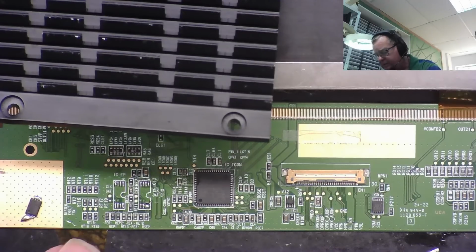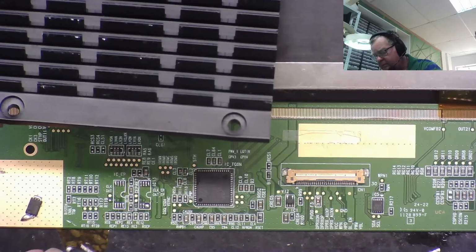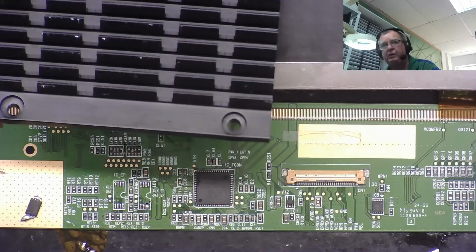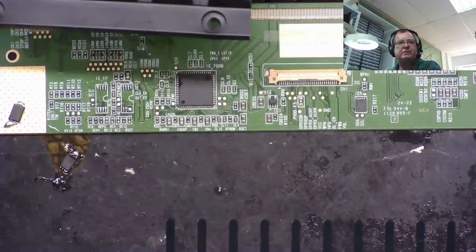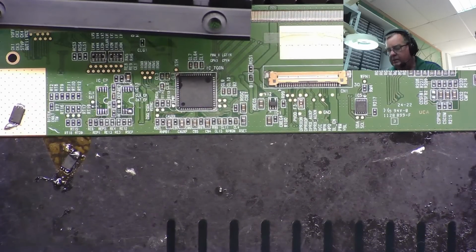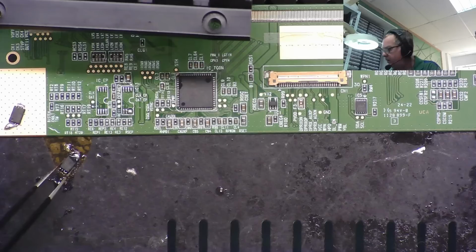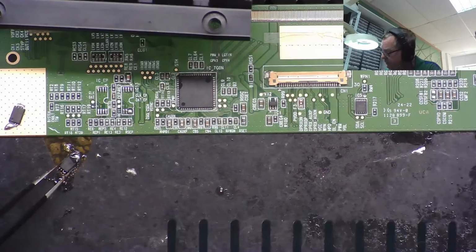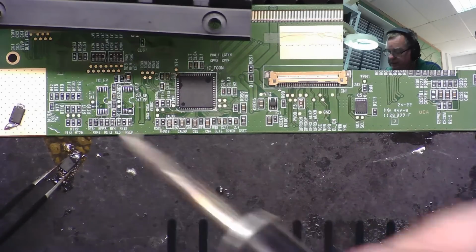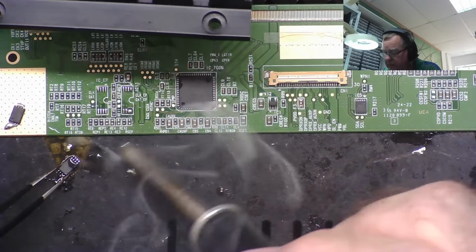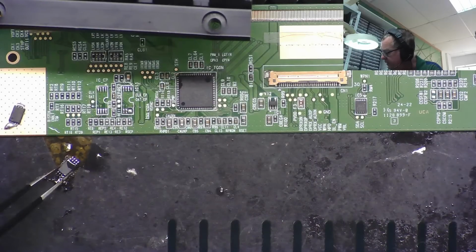So let's see if we can just clean up the pins on these now. This should probably come off quite easily just with a soldering iron. Probably don't need to use solder braid. Let's move this so you can see it. There it is. I shouldn't be able to show you this without blocking the view with my head. Okay, clean the end of the iron. Definitely clean the end of the iron. And that should take that off there.